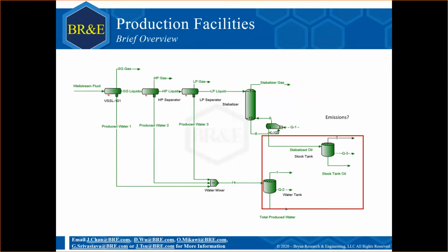The next consideration that ProMax can help you in is your breathing emissions. Now, we do have an air emission stencil, which is a simplified tool that allows you to calculate not only breathing emissions, which is the emissions that occur just from natural losses to the atmosphere over the lifetime in the tank, but that stencil also allows us to measure working losses as well, the losses associated with filling the tank.